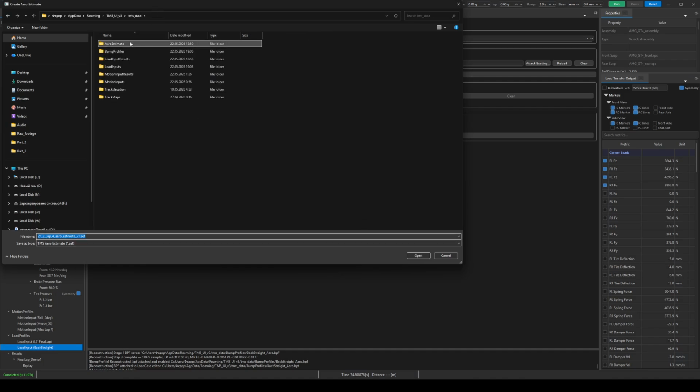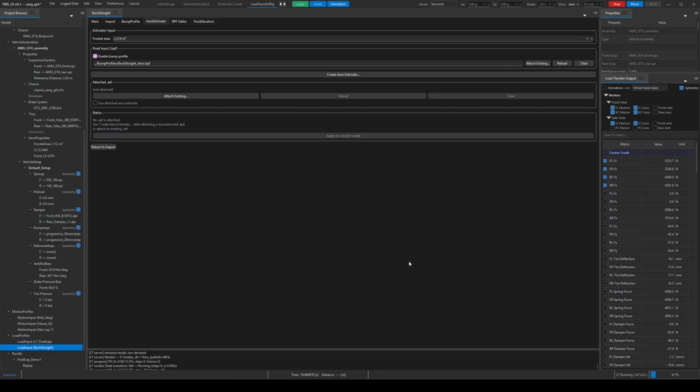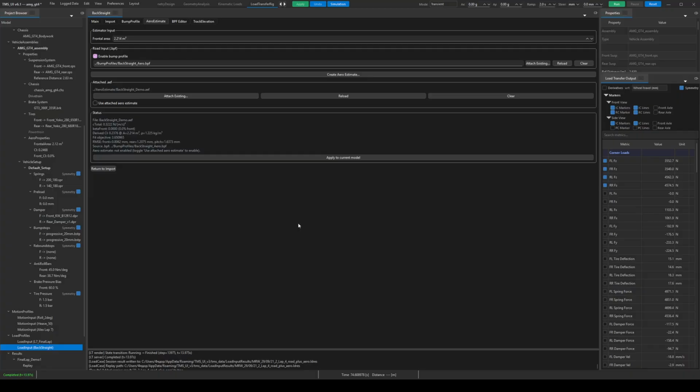The user selects a straight section of track, and the estimator treats suspension movement that cannot be explained by logged accelerations as aero-induced movement. It then adjusts total CL and front aero percentage until the simulated damper displacement better matches the logged data. The next stage will extend this into a more detailed estimator that derives a ride height-dependent aero map. For this vehicle and data set, the Stage 1 estimator gives CL equals 0.247 and front aero percentage of 0%. The result is written into the project tree.